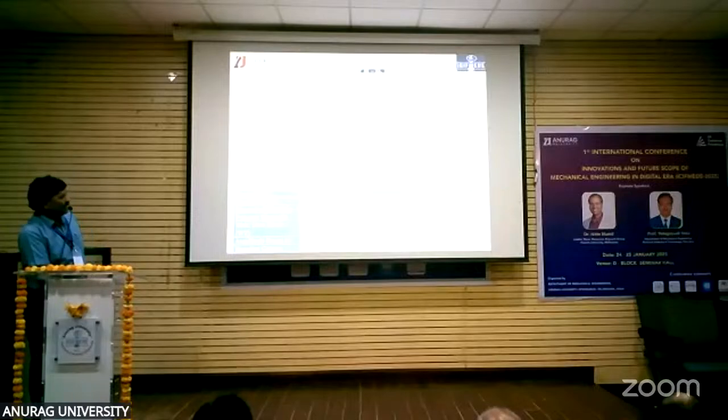In the TLBO algorithm, I considered a population size of 30 and 100 iterations, a pressure range of 2.5 bar to 4 bar, which I gave earlier, a weld time of 2 seconds to 3.5 seconds, and amplitude. The stopping criterion is a maximum of 100 iterations.